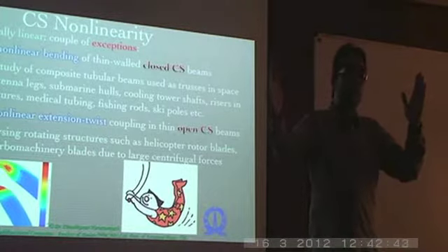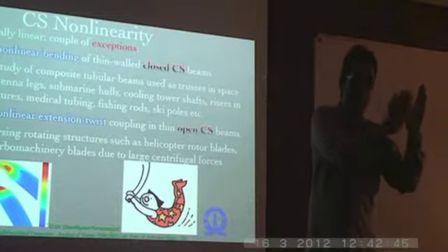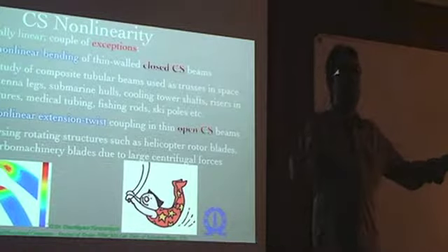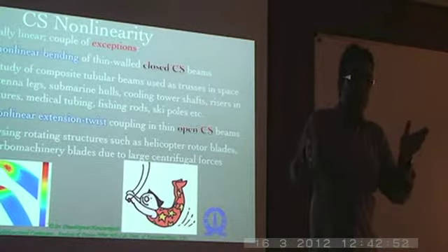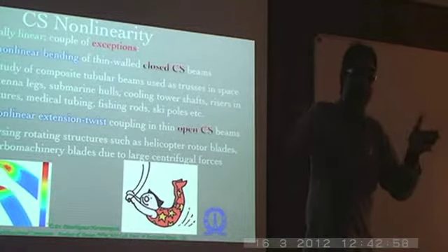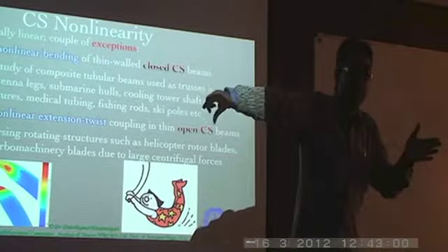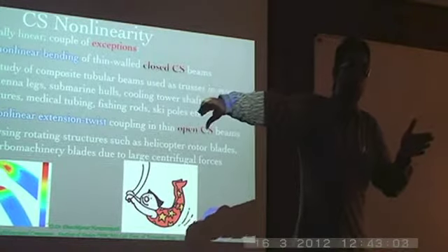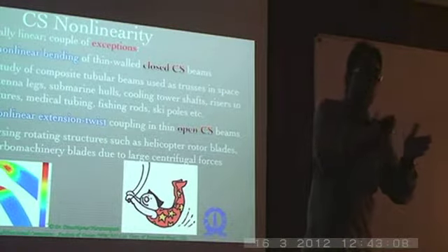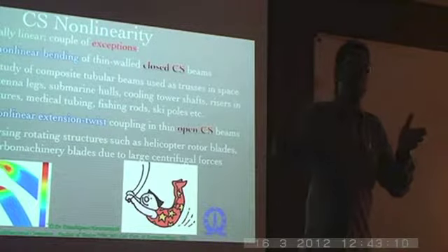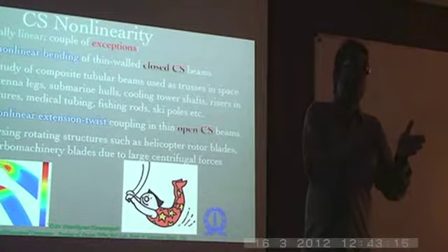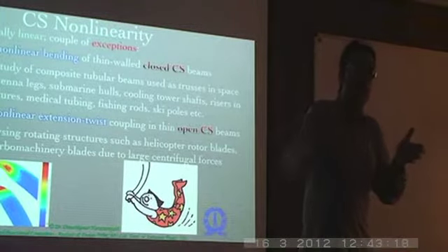One thing of course is the bending moment is varying along the length. That's something which will be taken care of by your 1D analysis. It's not something which is going to affect your cross-sectional analysis unless and until your cross-sectional shape itself changes along the length. For example, a tapered beam. Most aircraft wings basically have a taper with a smaller chord at the tip compared to the root. So in such a situation, you'll have to have different cross-sectional analysis at different locations. But it is not because of the difference in the loading value. It is more because of the change in the cross-sectional geometry and or material distribution.